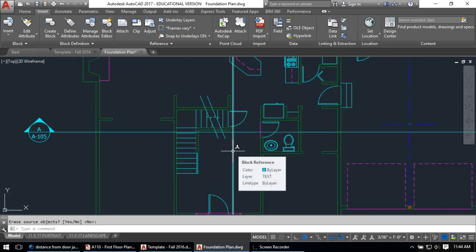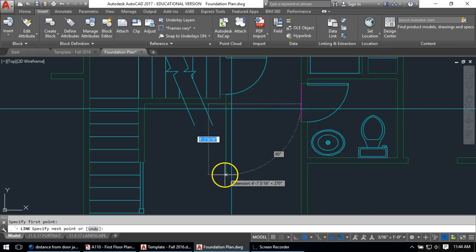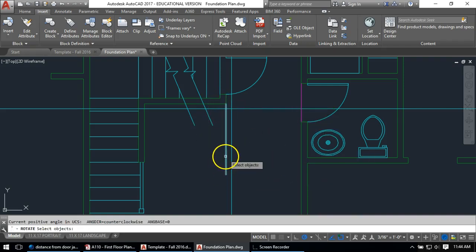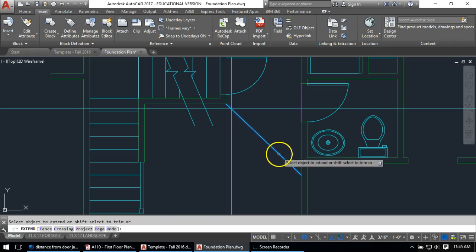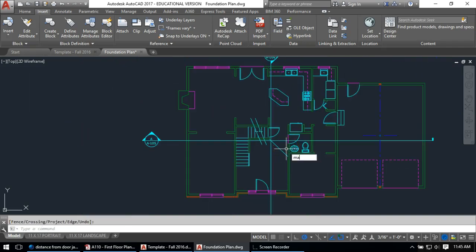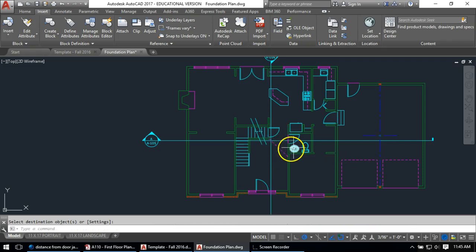There is a line that says edge of upper floor right here. Presumably it's a 45-degree line from this corner. It's not clear. Again, if I had the second floor, I would know it. But that's what I'm going to do. I'm going to set this, rotate 45 degrees, extend the line over, and then make it on this hidden line layer that I've been using to get it to be a dotted line. So I got that line there. I think that takes care of most everything on the inside that's not a note.